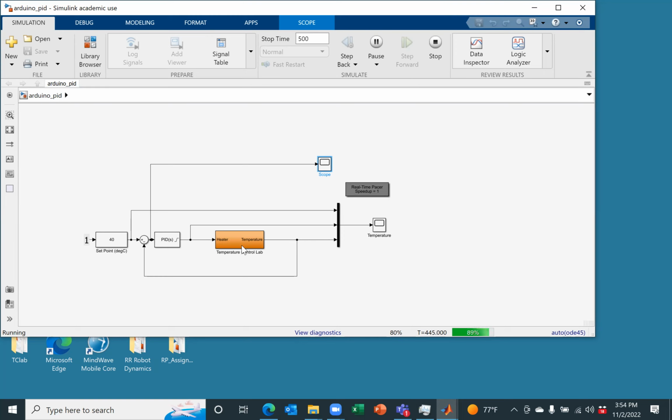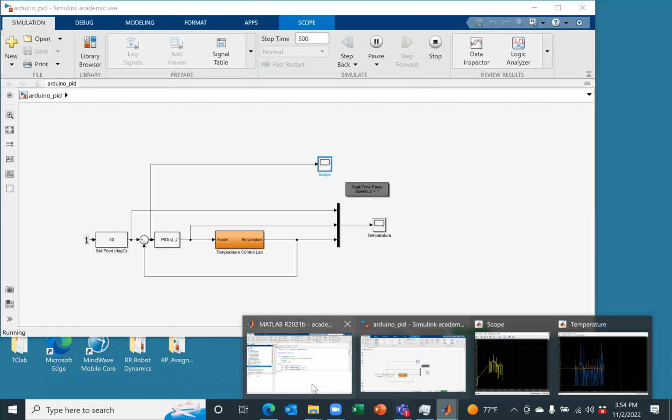Everyone understood this? Is it possible to use optimization to tune the PID? Yes, actually, if you look at the Control System Toolbox, there are optimizer tools. They use the linear optimization tools to tune the PID. But the problem here is this: for any optimizer to run, you need an optimization criterion. For example, you have to specify it has to be minimum time. It has to be minimum overshoot. And many a times, you may not be able to find an optimized solution.